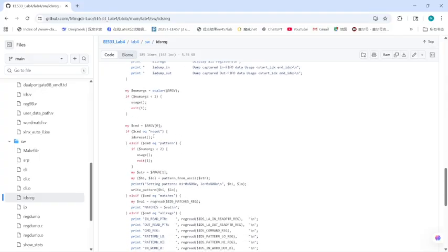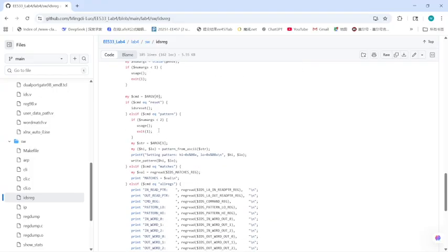Okay, so the reset command resets the match counter by writing 1 to the control register and then coming back to a value of 0. And the pattern command receives an ASCII string up to 7 bytes and converts it to a 56-bit matching pattern and an 8-bit mask. Then it writes these to the pattern high and pattern low registers for the hardware matcher to use.